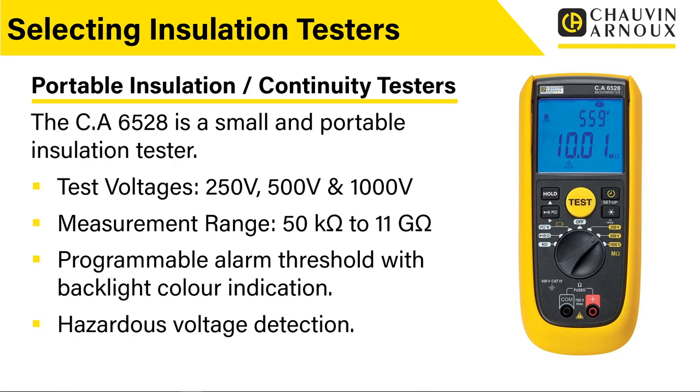You've also got the hazardous voltage detection built in. So if you connect this up to an equipment and the circuit or equipment you've connected up to is still live, again, it will warn you of that, and it won't let you carry out the test while that dangerous voltage is there. So again, that's a great safety feature built into this. So this is an entry-level product. This is really a sort of starting point for us with insulation continuity testers, but it is a great product. It's very portable, very easy to hold in the hand, and really a great addition to any maintenance electrician's toolbox, or anybody who's just starting out in doing this sort of testing where they want insulation but also a continuity function.